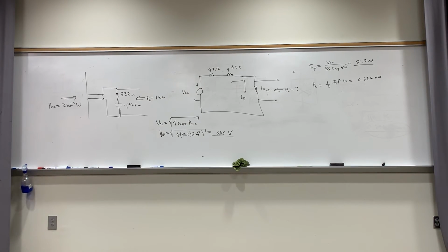Then after that, we did the Friis transmission equation. Do you remember we took energy from one antenna to another? And you had to be aware of the polarization mismatch. And we had to be aware of the fact that if you have 2 antennas like this, both say half-wave dipoles, then you have to actually know the angle that the signal's coming in to that second antenna, because this would be for maximum gain, right?